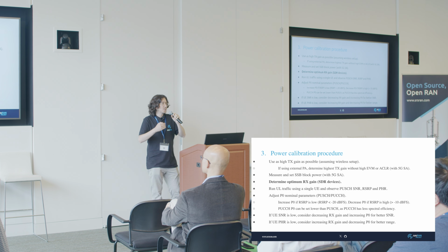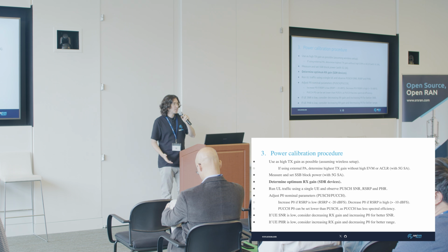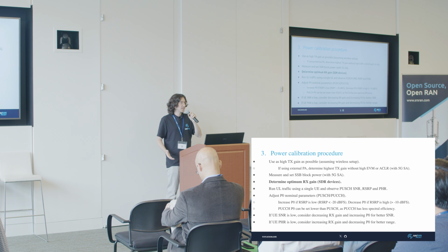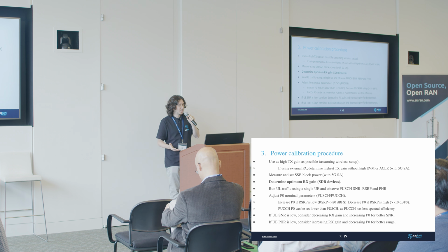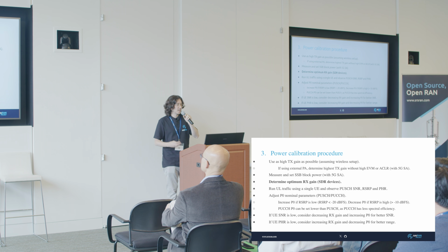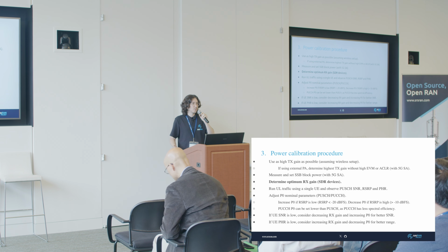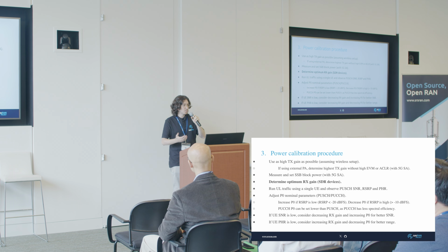Well, it means that you can keep increasing the transmission gain, but there will be a point where doing so will result in signal saturation in the downlink. And in case this is the limitation you are facing, the proper way to find the limit is, again, to use a 5G signal analyzer where you can see a metric of error vector magnitude, or EVM, and also the out-of-band emissions, because as you know, these are the two main drawbacks when you have saturation in a transmission chain.